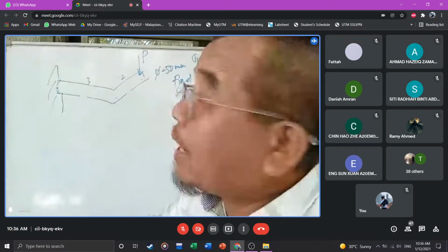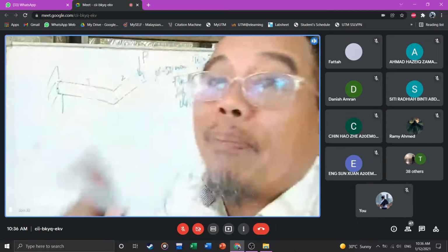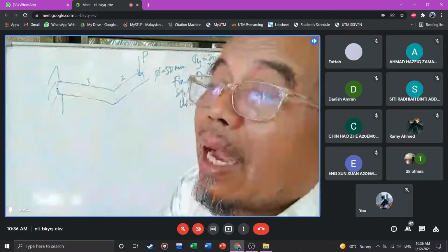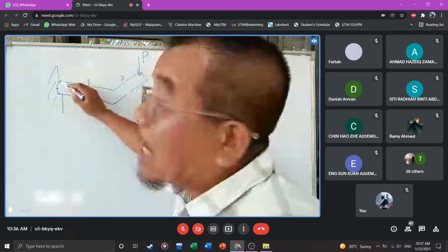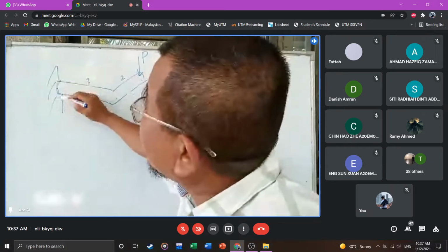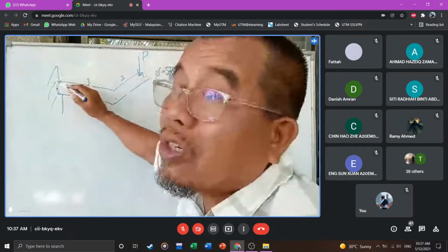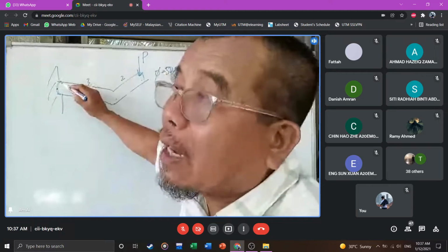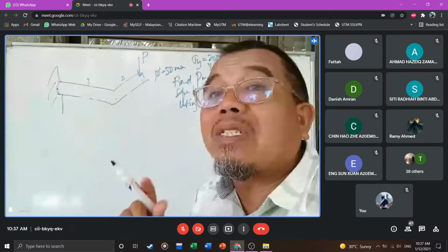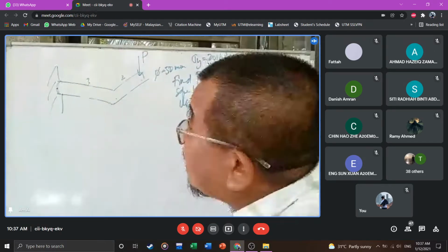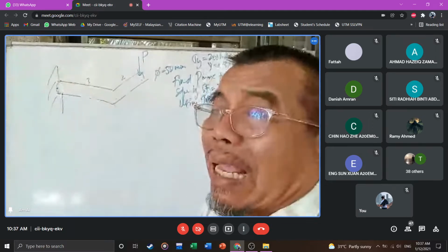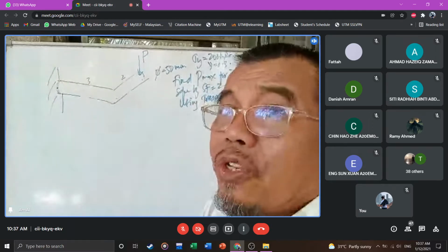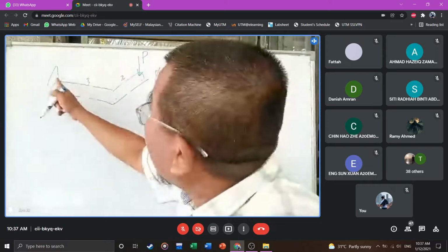Yes. And then you decide, the top one is the most dangerous one. Why? The maximum tensile there and the torsion is everywhere the same. So we have a torsion or shear stress with maximum tensile. That's how you decide. You must see how it's getting the stress there. You must visualize and then you make a decision. I have to cut there.